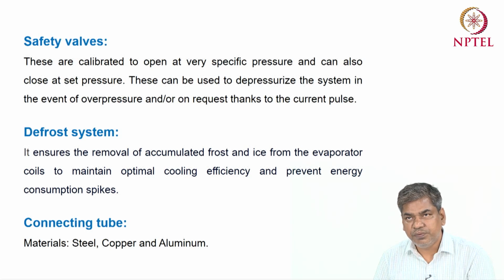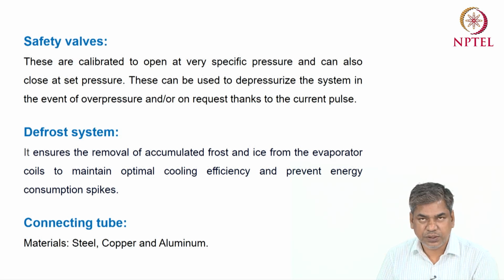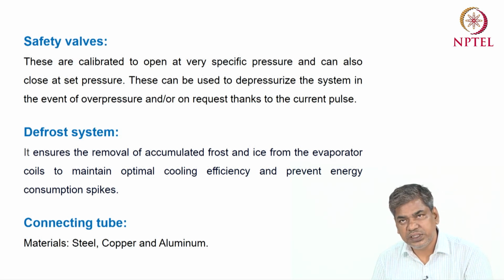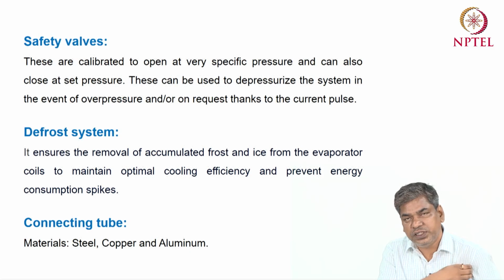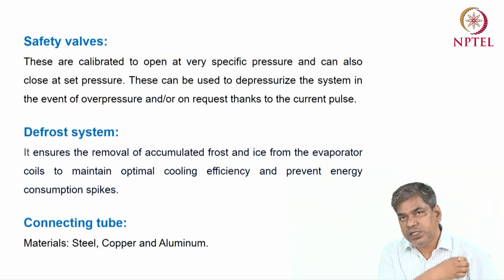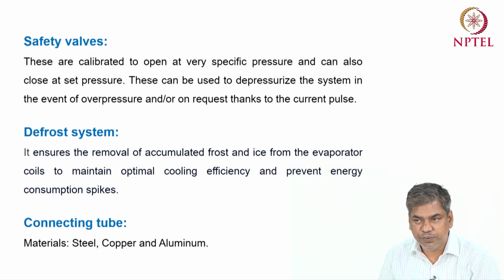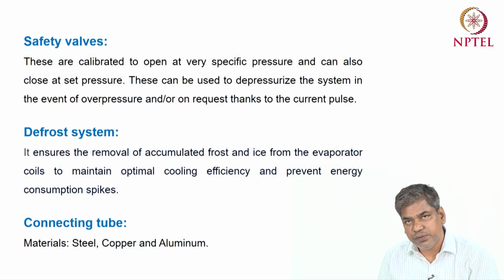Okay, so sometimes we can use it to depressurize. This safety valve can be used for safe operation on the high pressure side and safe operation on the low pressure side. In the case of the high pressure side, this is the high pressure control or high pressure safety valve, and that may also be a low pressure safety valve. Okay, so if the pressure is higher than the allowable pressure or safe pressure, that is a dangerous situation. If the pressure is lower than the design condition or the safe condition, that is also a dangerous situation.